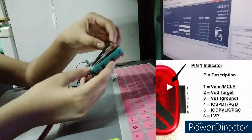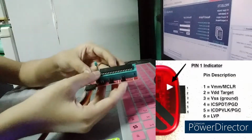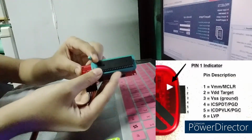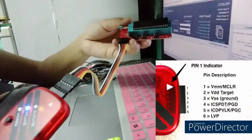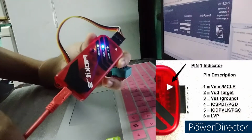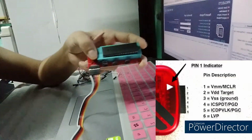So let's connect it here. Just put our 40-pin IC here, and then this one, we will be pulling this down to lock our IC. So as you can see, our Microchip adapter is connected to our PICkit 3 here, which is also connected to our MPLAB IPE. So now, we will be programming our IC.